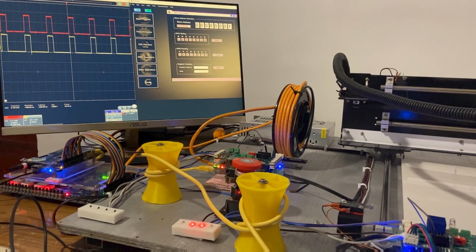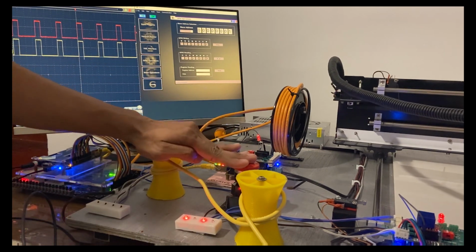Output pins of slaves can be configured to switch to a predefined state in an emergency. These configurations are stated in the XML file. In our case, pin 0 of slave 6 will go to high state and pin 1 will go to low state in an emergency. Before pushing the emergency button, pin 0 is in low state and pin 1 is in high state. When the emergency button is pushed, pin 0 of slave 6 goes to high state and pin 1 goes to low state, and this is indicated in the LEDs.